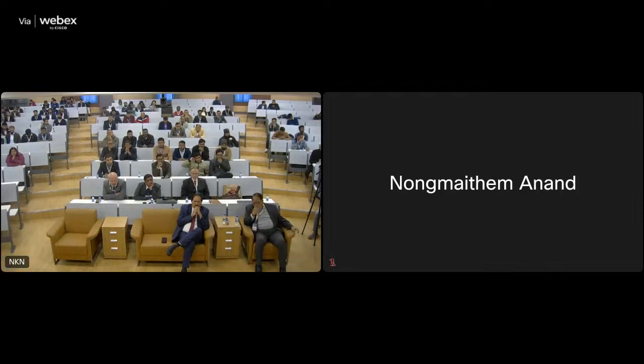Tunnel excavation results in the widening of joints and creating new fractures near the excavated periphery, like an excavation damaged zone. So it is expected that the grout will percolate through these fractures, and so we can have a grouted zone. So rock blocks will get cemented. As I have told you earlier, how is this going to reflect in the Q? That means RQD shall again increase around the tunnel.